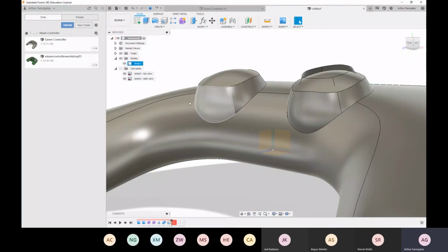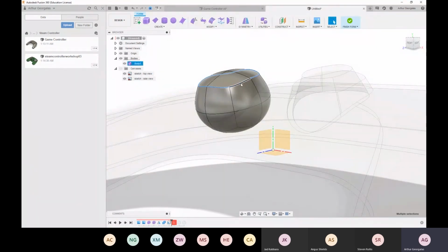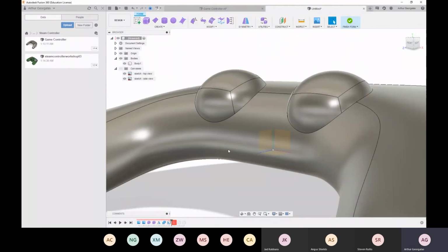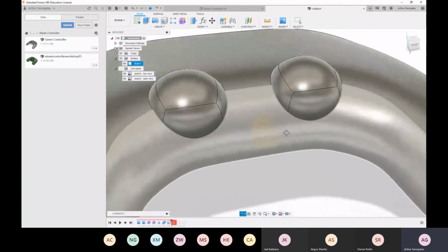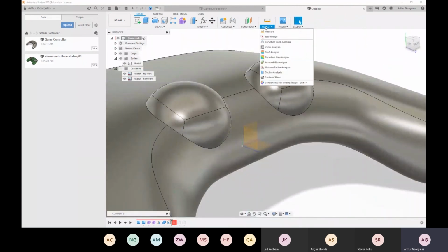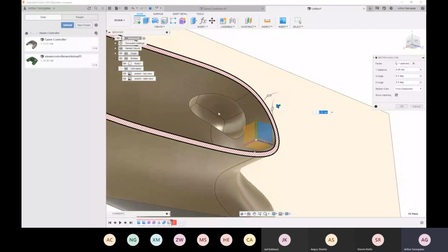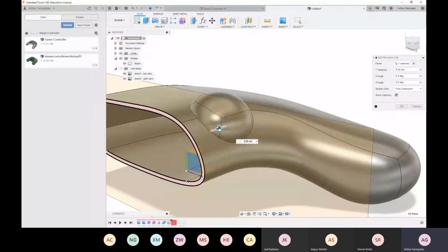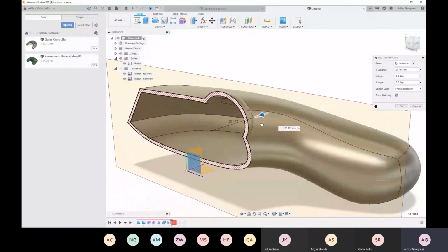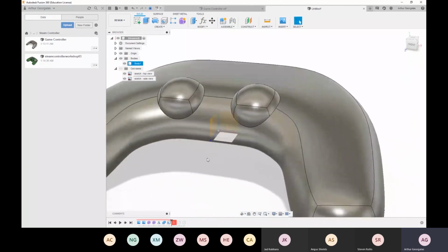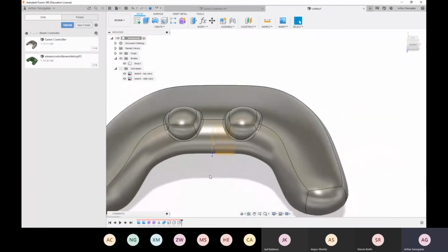Okay, it really doesn't like that quad ball, so let's just go back and uncrease that. Okay, and of course it works perfectly now, because why not? So if we go section analysis, there, it's all hollowed out. We can see that our quad walls are hollow as well. And that all works really well. So we can go through and add in these fillets now or whenever, it doesn't really matter. But yeah, just know if there's problems with the shelling, most likely it's to do with a fillet or a weird edge or something like that. It's not really a big deal.